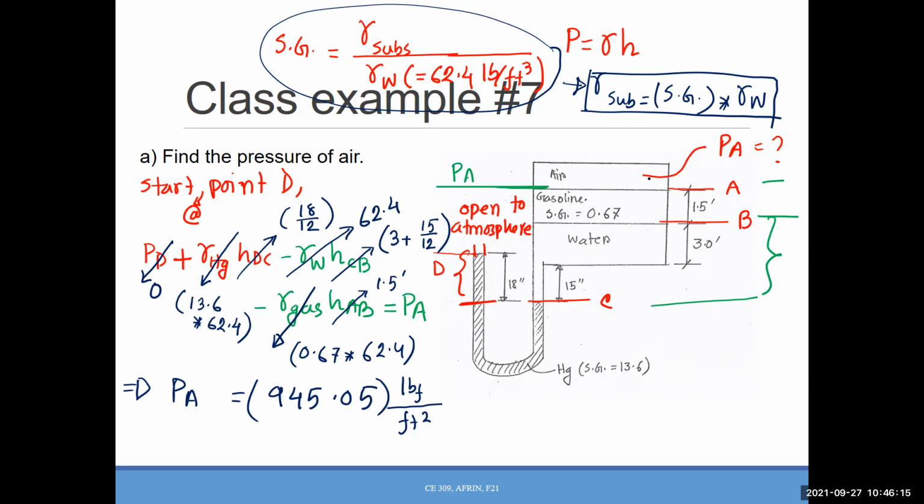That is the pressure here because of all of these, and just using the simple manometer rule, we could calculate the pressure. Now, before I go further, please tell me that you are comfortable with that. Otherwise, I will explain this class example again. Are you getting the idea, why we're doing that and how to do that? Okay, good. So basically, we are calculating the pressure for each fluid level layer, and then we are just adding or subtracting that, right?